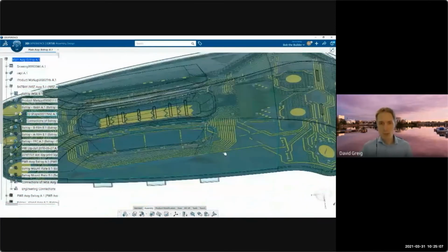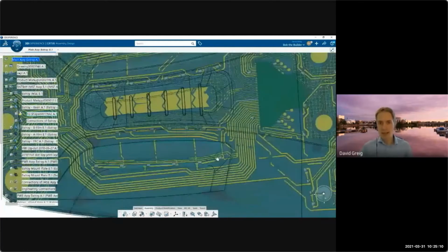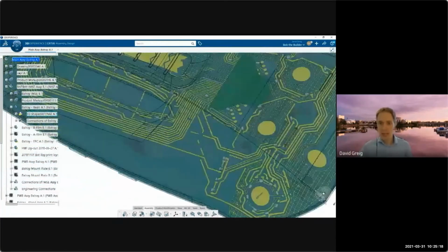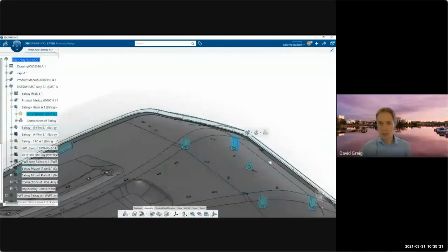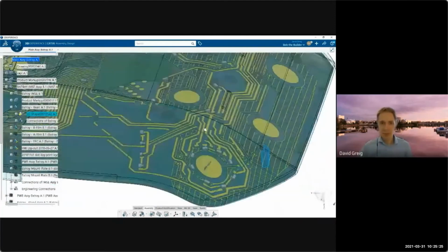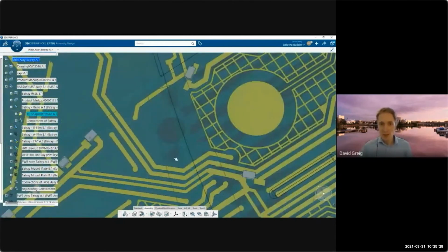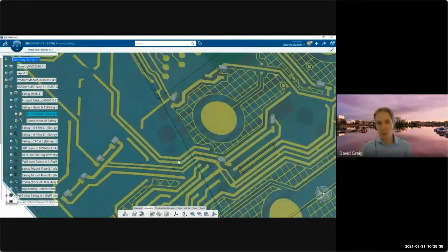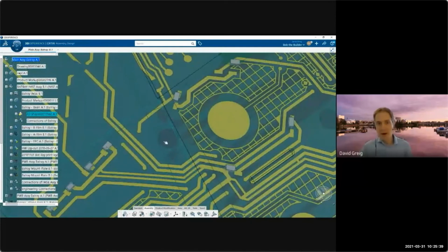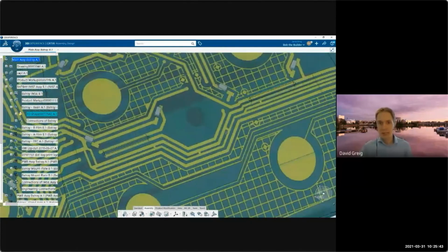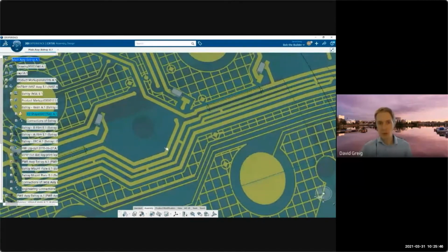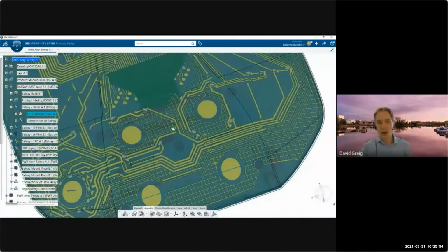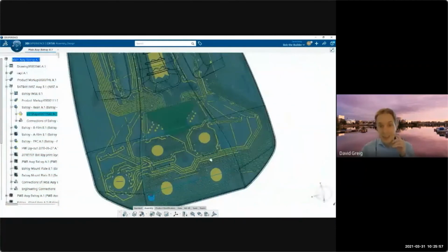Like Tuomas was just mentioning about the traces and the width around them having to be increased to account for the current. And when traces are changed, we have to make sure they don't interfere with any of the screw tower positions. So we have our fixing locations, and coming close to there, we need to have clearance between everything, because during production, all these traces move and shift with all the forming and injection molding. And we have to make sure that none of them fall into these fixing features. So even if Tuomas wants to make a new tracing proposal, or if I want to move one of these towers slightly, we need to mention it and re-share our layouts with each other to make sure that nothing is interfering with each other.